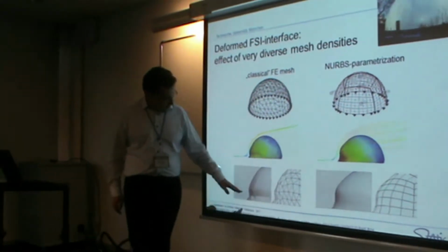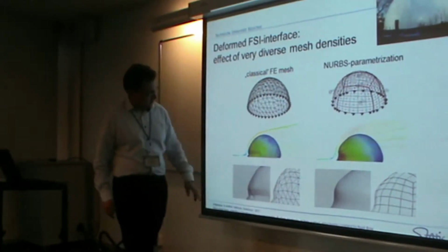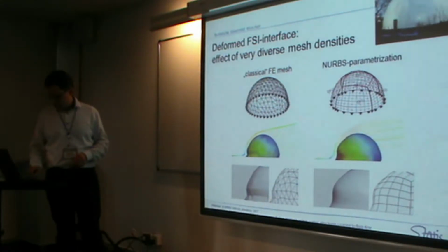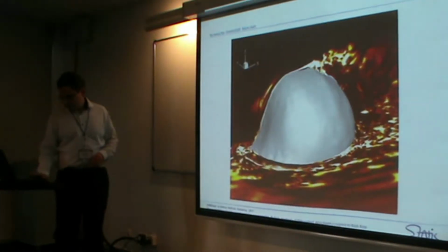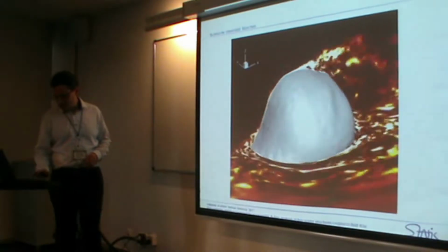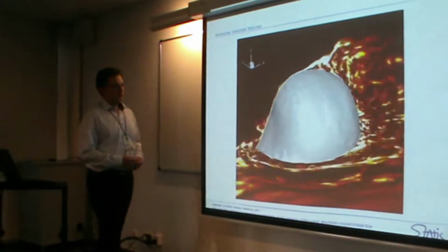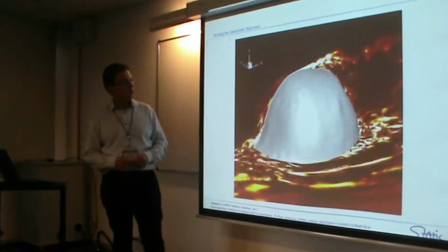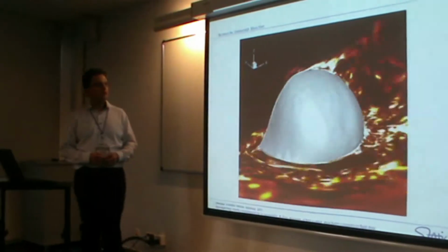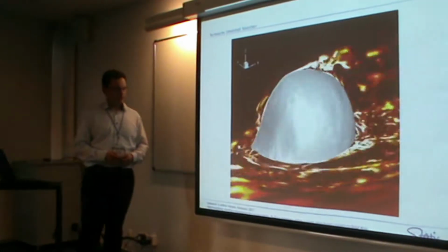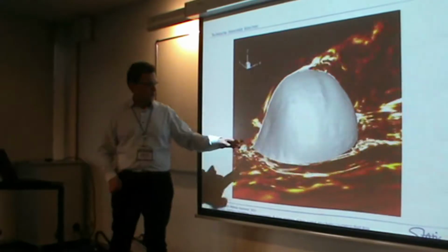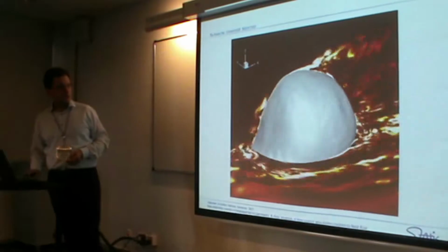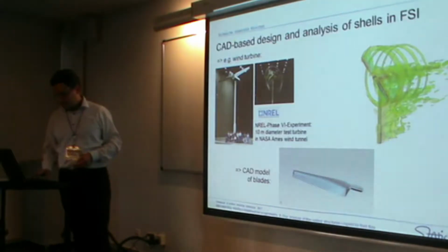You see already that due to these kinds of faceting errors, we definitely have a change in the surface conditions for the flow at the FSI interface. Here is an animation with an intentionally not so nicely resolved bubble in an LES simulation. You can imagine, if you see these vortex structures here, the resolution, which was done by Guillaume Dénaya, is very fine, even excessive, and so every small discretization kink is nicely resolved, but it's an artificial resolution of kinks because they should not be there.